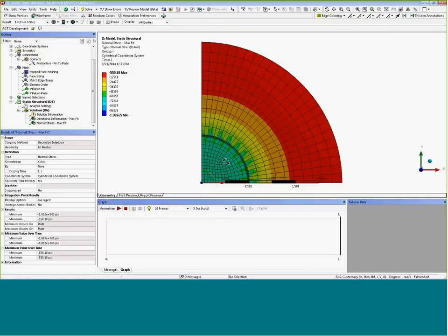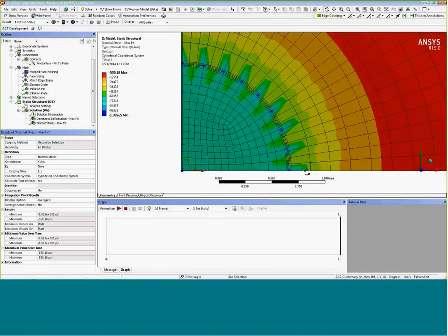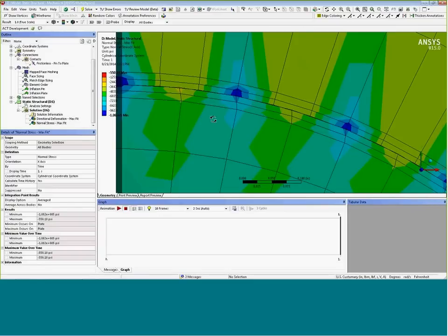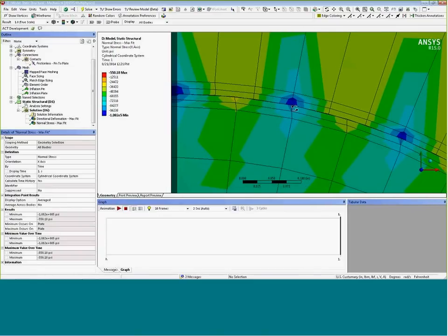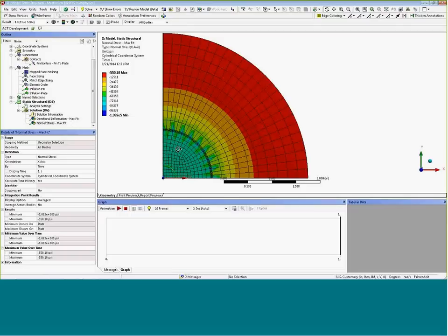And we look at the results now, and we see that they're quite poor. I mean, this is 108 KSI, and the results around the circumference are highly irregular. So we're getting very sharp or high isolated stresses at those sharp points. And that's just due to the lower order mesh that we're using. So that's not the best answer to this problem by any means.